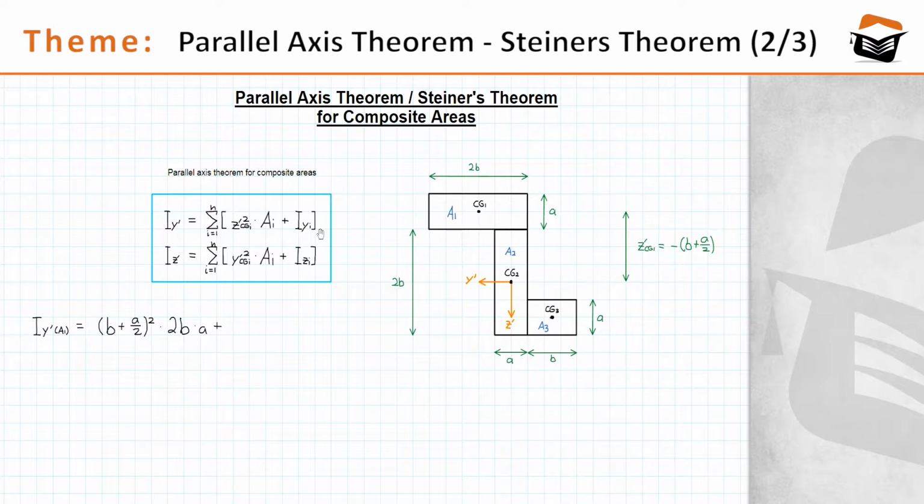And that value can be obtained from tables, but if you have watched the first video, you know that to calculate the area moment of inertia of a rectangle where the reference axis is the centroidal axis, you have to do, let me write it down here, I sub, well, let me just write down y1, just to indicate that we're dealing with an axis that is the centroidal axis of the first partial rectangle.